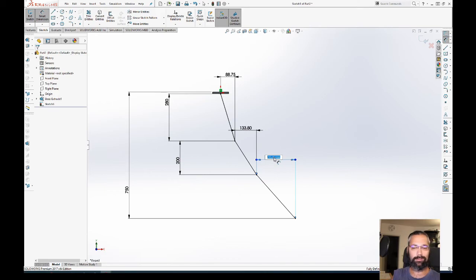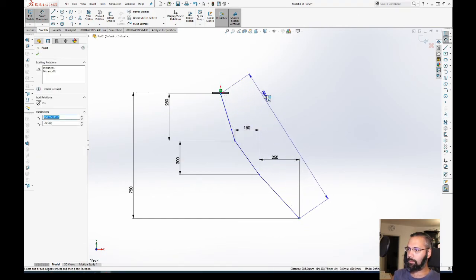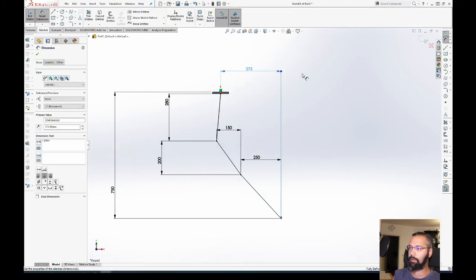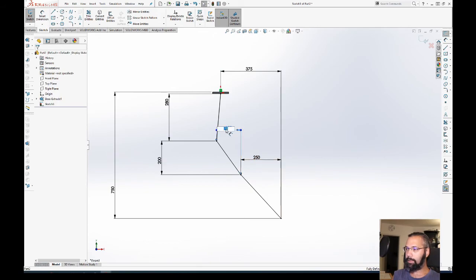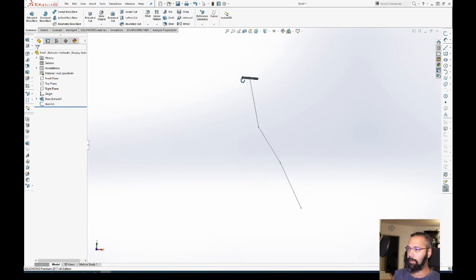This will be an iterative process. And actually, let's do it like this. I said that my table was 750 in diameter, I think, so let's do 750 divided by 2 and then change this to 150. Cool. Now you have one sketch.